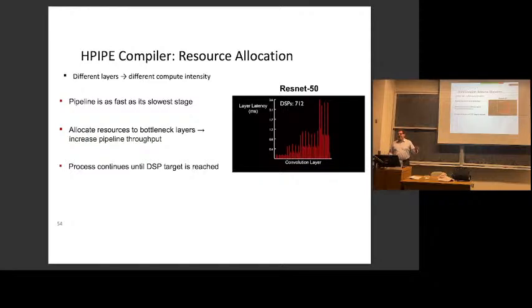Okay, this architecture then would not work in that chip, but generally we don't hit that. And then it starts allocating more resources to the slowest layers. So it's going to look at these ones out here and say, those are my problems, start allocating resources to them. Eventually this chip has 5,000 DSPs in it. It has increased the parallelism settings on the later layers, so the parameters passed into the final hardware generator, to the point where the latency of all of the layers is pretty close. And also pretty low, right?